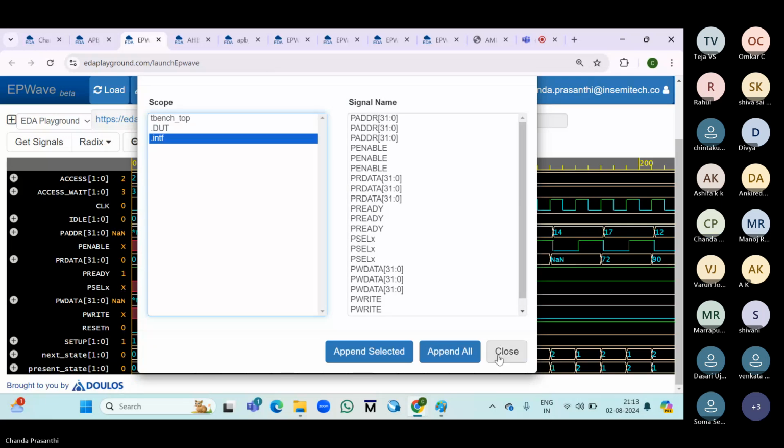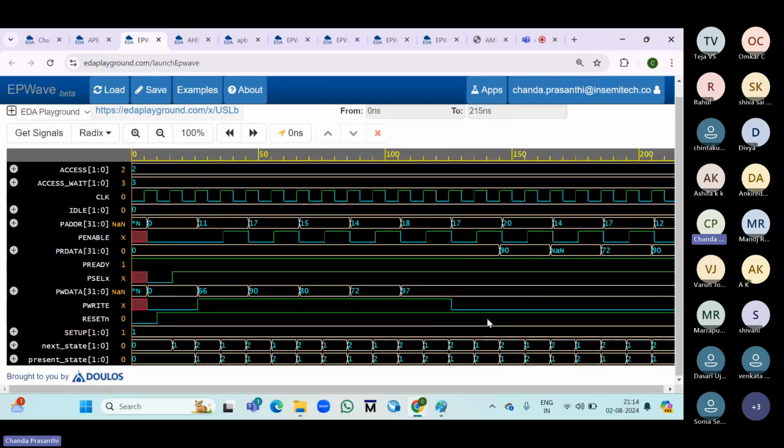So which one do we usually select, DUT or interface? Interface signals and any signals are the same. DUT signal means we check the driver to DUT connection. Interface signals means after getting to the monitor we can check the testbench top level; the monitor is receiving the data from the DUT, and we can check that data. DUT means until the driver. Correct. Okay, got it. Thank you.